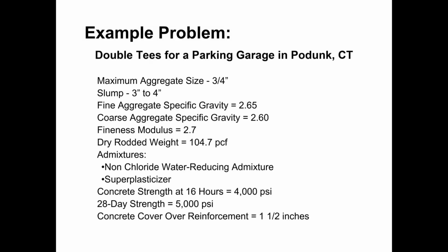design development. One thing that you probably already picked up on in the previous example mix design that Chance did with you yesterday is that concrete mix design development is as much art as it is science. The guidelines that we use in developing concrete mix designs are really just intended to get us close to where we want to be with the material properties of our mix design. They're not really intended to give us a fine-tuned mix design. The process of getting the design to the point where it's really useful to us comes through the trial batching